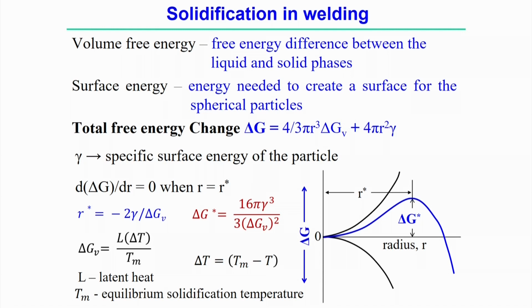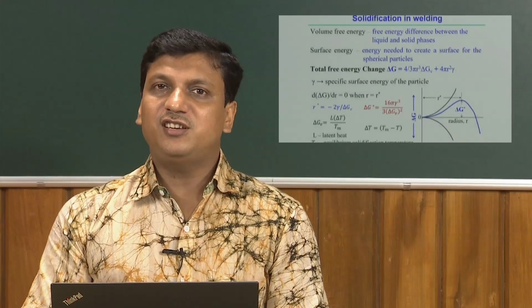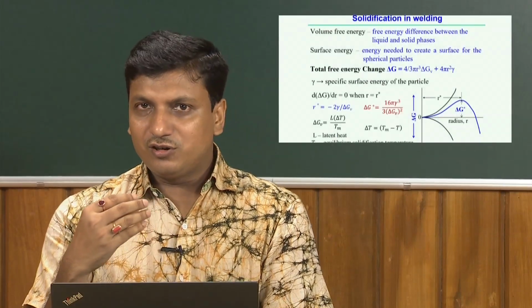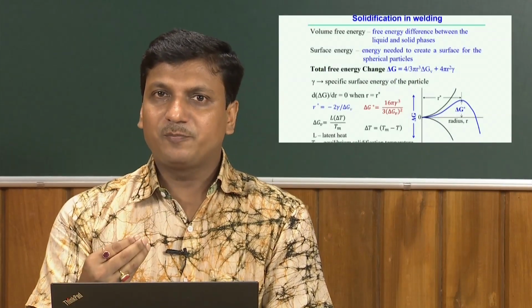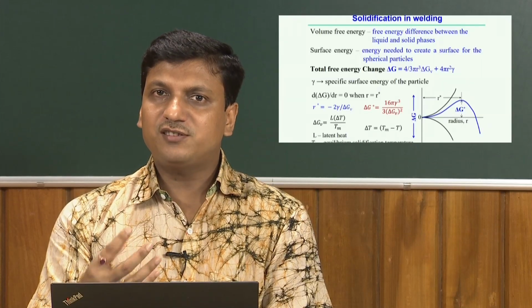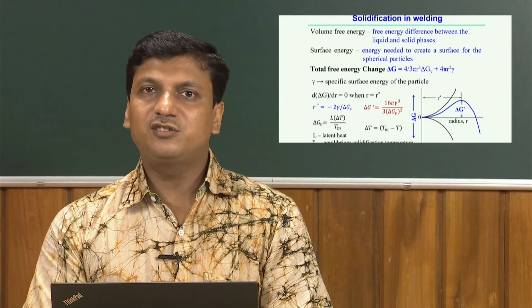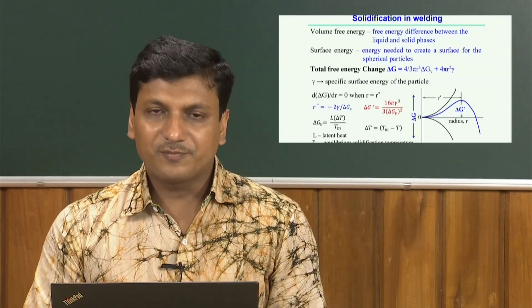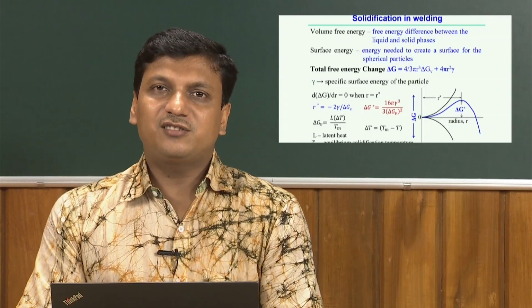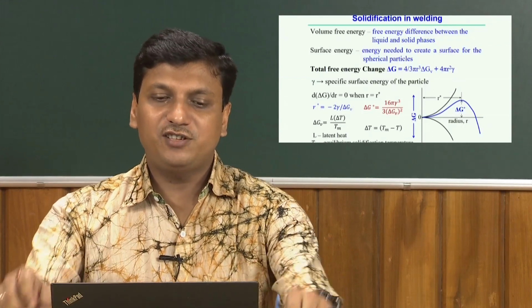Now, if we define the volume free energy, that is the free energy difference between the liquid and solid phases, because during the solidification process there is a change of the liquid to the solid phase. So, during this change of the phase, some amount of volumetric energy is required to change from liquid to solid. That can be defined as a volume free energy.